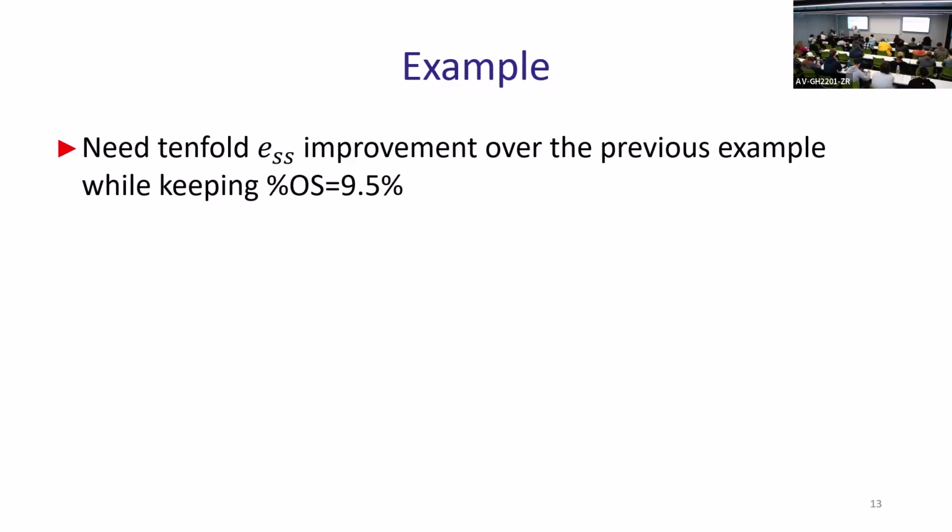And this will be whatever the gain is divided by whatever the first pole is and whatever the second pole is. Okay, this is your DC gain. If you want to improve it 10 times, you just multiply that entire DC gain by the same number, which is 10. In that case, you want a 10-fold improvement. So your KV will be multiplied practically by the same number, right?